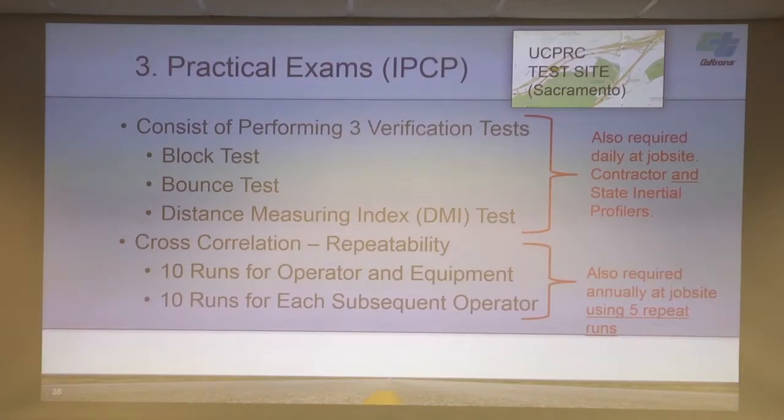They also have to do this. If we can't pull up these records when we run a verification, they didn't do the certification, so that verification's no good. So we have to have those records daily. Every inertial profiler operator has to go through this block, bounce, and DMI test daily, to certify that the equipment is working correctly.